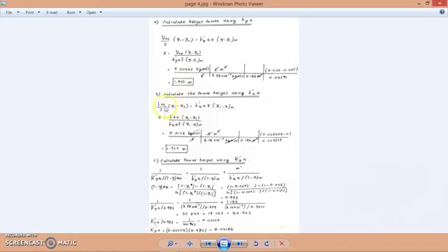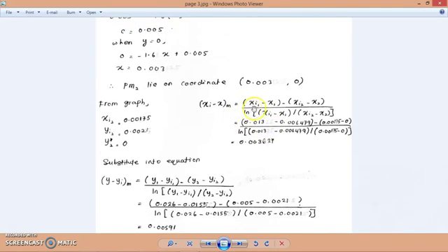And next, to calculate Z using the single phase mass transfer coefficient in liquid, you have to find the value for xi minus xm, and the equation for xi minus xm, you can see over here, is (xi1 minus x1) minus (xi2 minus x2), and so on.